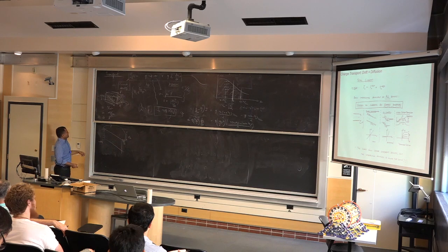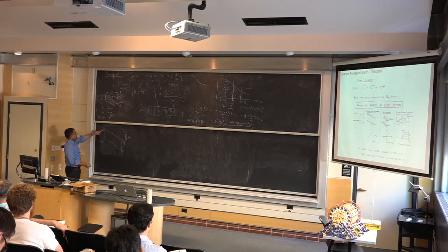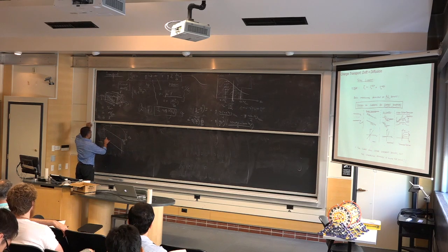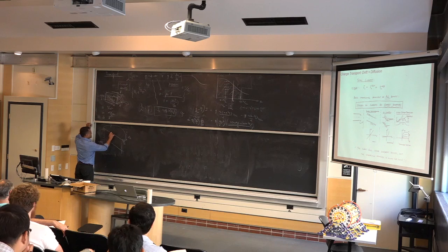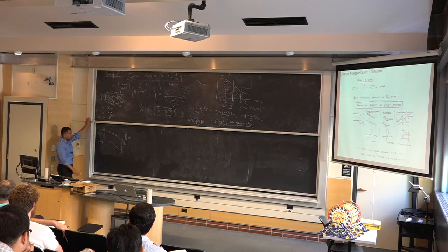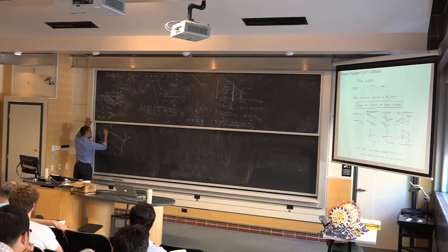And let me just see whether I drew this correctly. So this is a situation where, how do I know whether I drew it correctly, when I draw the battery like that, it looks like here's positive, here's negative. But I think this is not quite right, because you see electrons in this situation will stream down this way. They want to go this way. Why? Because deep in the semiconductor, this is a band. This is the band edge, EC. And above it, as we saw, there's a bunch of energies, right? This is a band. These are all energies allowed for the electron.